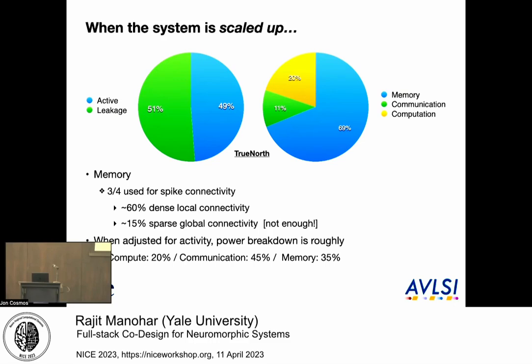is 20%, but of that, about half of that is a routing table lookup. So the total compute on this chip is like 10% of the system power budget, right? So it doesn't really matter. You can make that 0 and you'll get a 10% improvement, right? So your beautiful new, extremely well-engineered device, great, 10%, right? The other 90%, nothing happened. And it's just sad. This is why the semiconductor industry is doing what it's doing, right?